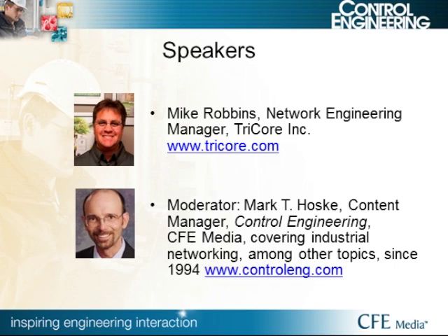If you need to do a long run of cabling in a noisy environment, you may even consider going to fiber cabling. If you're within a plant, you can use multimode fiber cable, which will give you a distance of 2 kilometers, and it's absolutely immune to any noise out on the shop floor.